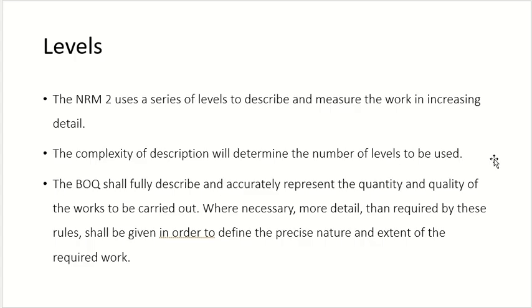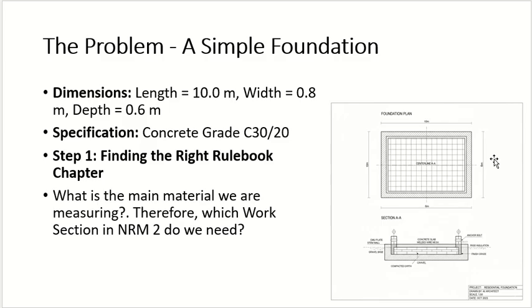In the end, when you prepare a BOQ using the standards, it should tell you about the quantity of material and the quality of material, both, if you are following the standards. But it is not fixed. Whatever is given in the standard, you have to incorporate it in the BOQ, but more details should be added wherever required or wherever they are given. So you can do more, you should not do less.